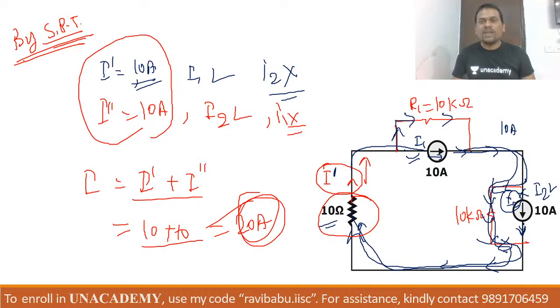So see, beta, in this situation the circuit is not correct, or the circuit is not satisfying the superposition theorem. In practical life, we do not design that type of circuit in which two current sources are connected in series. If we want to design such a circuit, it is to improve the voltage level. Please mind it, beta, here at any cost the superposition is not applicable.